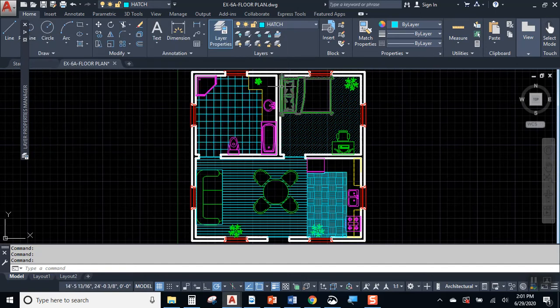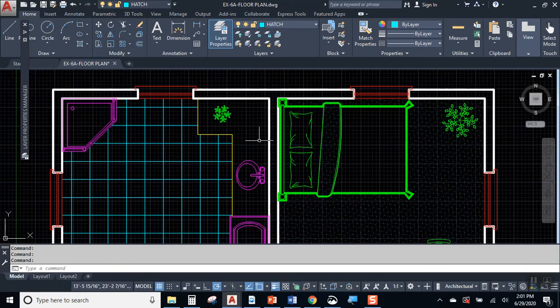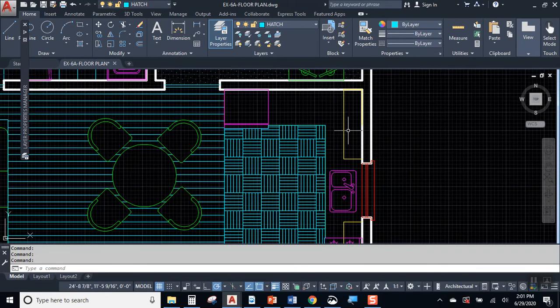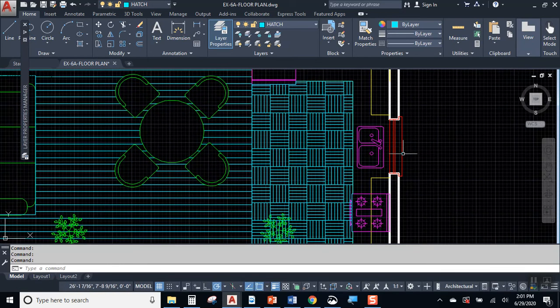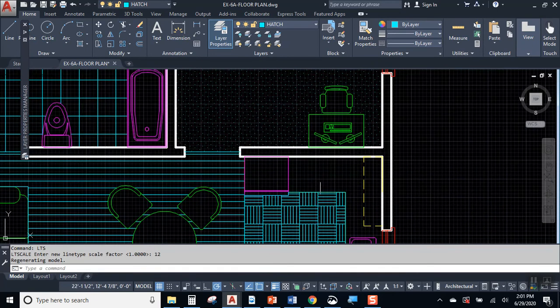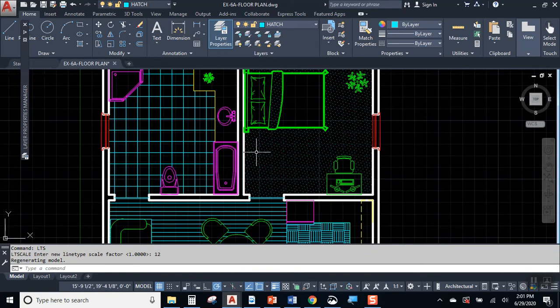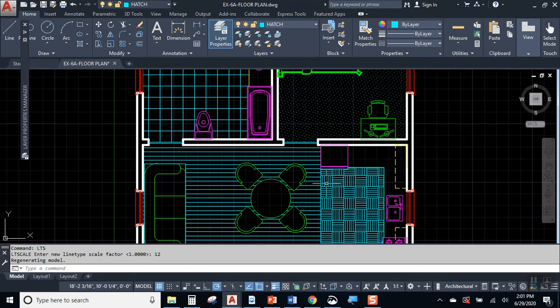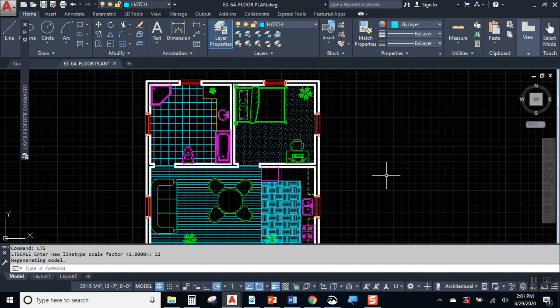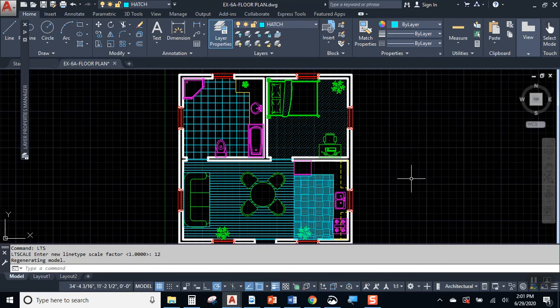We've talked about countertops with cabinets underneath and countertops that have cabinets above, and how to change that LTS, that line type scale, in order to be able to see those dashes. We've added blocks, we've made some groups, we've even added a hatch to dress things up. Okay. So a lot of stuff accomplished with this little exercise, and I think this is going to set us up well for the assignment that follows.